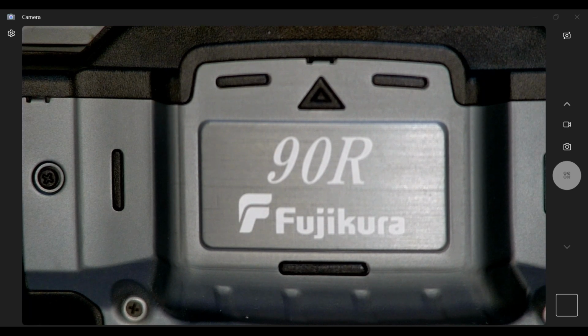We do have a PM, which we call polarization maintaining fusion splicer, that has not only X, Y, ZL, ZR, but it also has theta motion, theta left, theta right. That is a rotational axis motor that will allow you to rotate and align the stress rods within a polarization maintaining splicer. We do have that available, but not on a field 90 style series machine, version 90 basically.